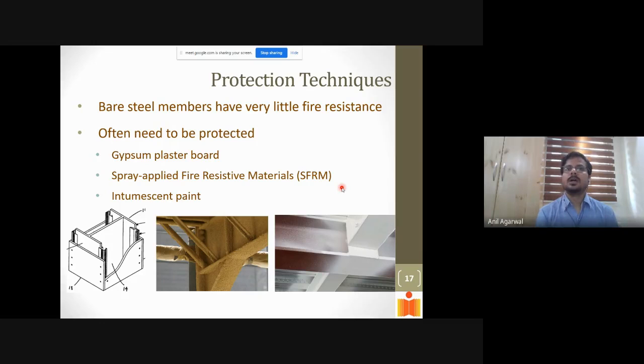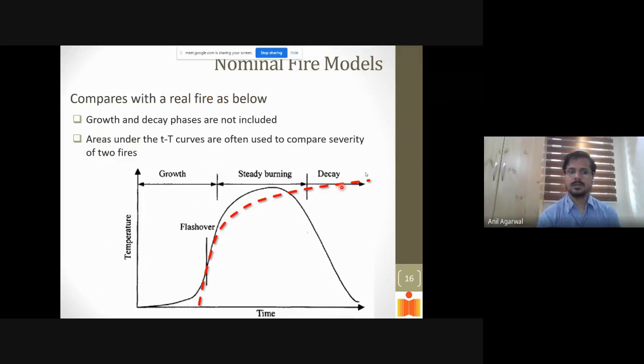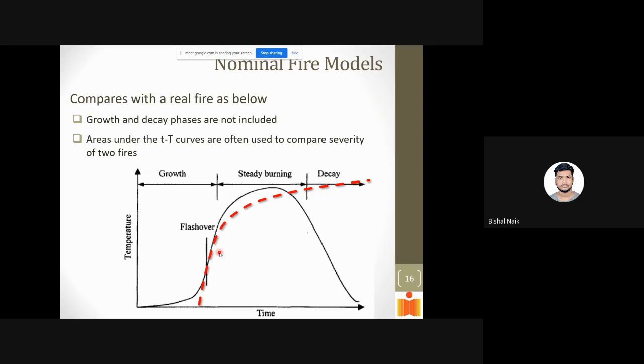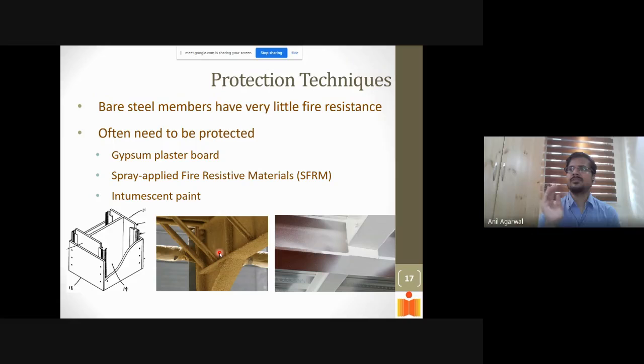We just discussed and saw that after half an hour, what will be the temperature of steel in standard fire? We discussed that. Lohit had said 400. Yes, sir. 650 we discussed. Yeah, it is more likely to be 650. So at 650, after half an hour, what will be the reduced strength? About 45%, right? And that is the load that is likely to be acting on the structure at that time.